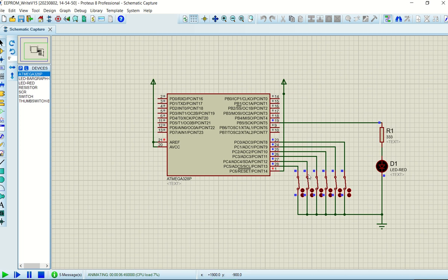At this stage, let me just close everything. At this stage, you see basically all zeros. If I open this, this is a 1 sitting on PC0, so the hex value is in actual fact 00 here and 0001, so it's 01. And you'll see that the LED is off. And I can change these inputs on port C, and you will see that nothing happens. It will only switch on if the value on port C is hex 28.